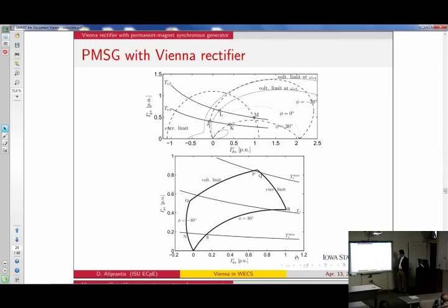So we did an analysis, and the analysis was based on simulation. We simulated this very, very carefully. We put in not only the generator losses, but also the losses from the power electronics, so as a system together. And we found which combination is best. We did basically the efficiency analysis of this entire domain, very, very carefully in the computer. My graduate student did. I didn't do any of that.